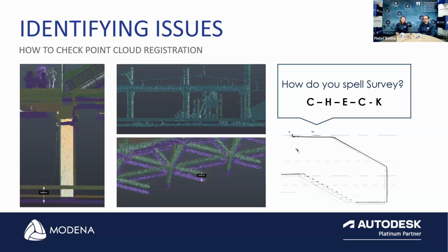As you can see there on the left hand side, we had some interesting data sets across our table before, where you can clearly see a misalignment in that data set. That's a clear indication that something has gone terribly wrong here, and you need to go back to site, and go back and check the registration and the processing.